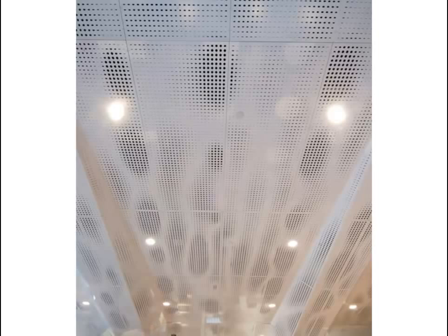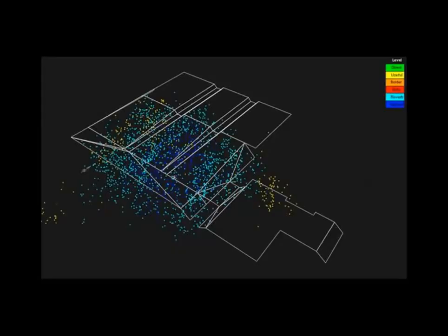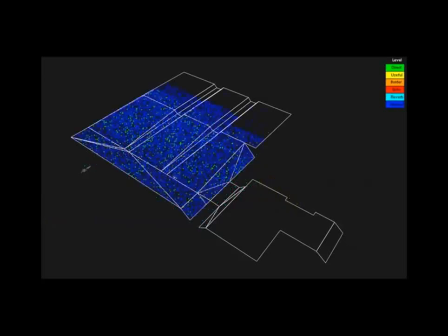So the acoustic panels in the ceiling were derived by taking an acoustic study using attractors and then propagating it to a series of custom fabricated acoustic panels. They had a simulation of the space, and they used sound generators to check the sound levels at various points. This is what ended up resulting. They had these hot spots where there was too much reverberation, and they wanted to lower it. So these little green pieces here are the attractors, where the sound concentrates.